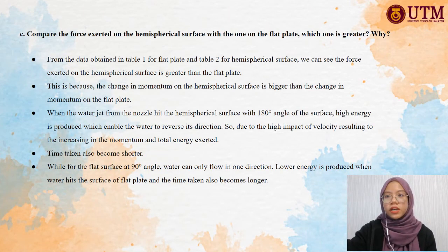Okay, I will proceed with the next question, which is to compare the force exerted on the hemispherical surface with the one on the flat plate. Which one is greater and why? From the data obtained in table 1 for the flat plate and table 2 for the hemispherical surface, we can see the force exerted on the hemispherical surface is greater than on the flat plate.